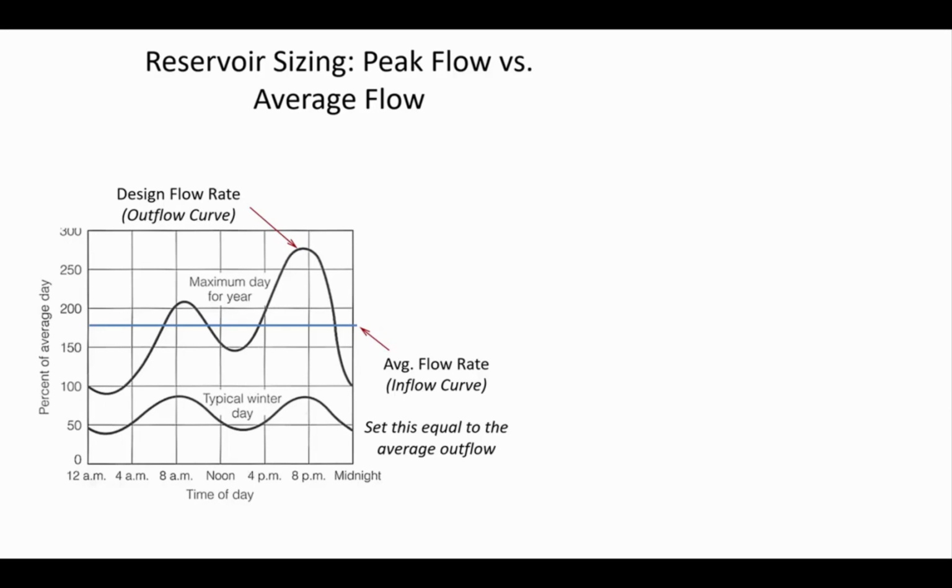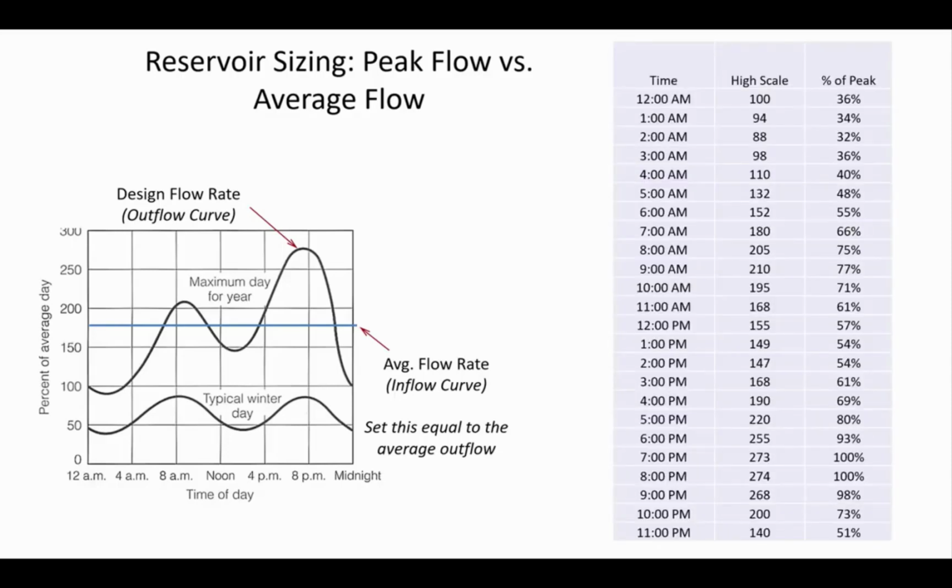So I think that this concept maybe will make more sense as we actually go through the spreadsheet, but the important thing to keep in mind is that we're going to design this storage tank so it's big enough for the biggest day of our expected design life. You know, 20 years in the future, when the town is all fully developed and it's having this peak demand experience, we want to make sure that the reservoir is large enough so that the city doesn't run out of water. Okay, now this is my attempt to digitize the curve.